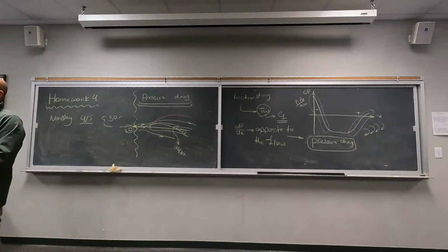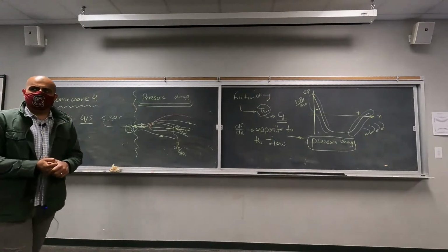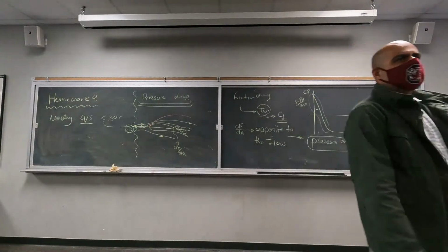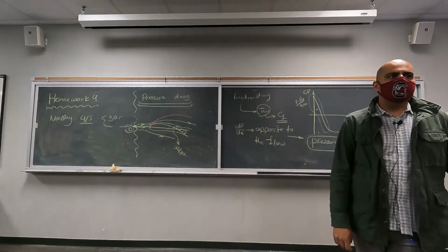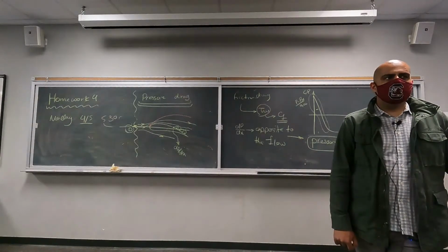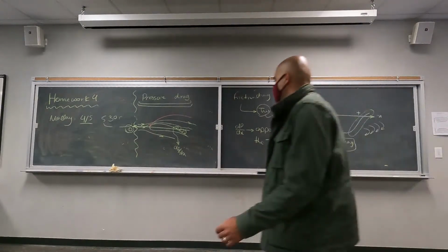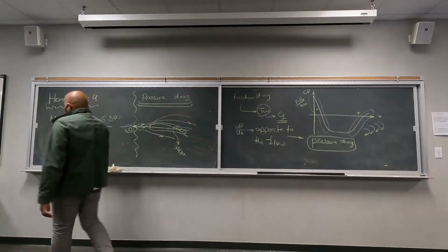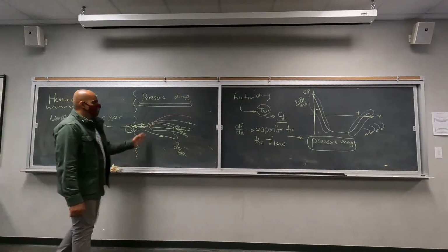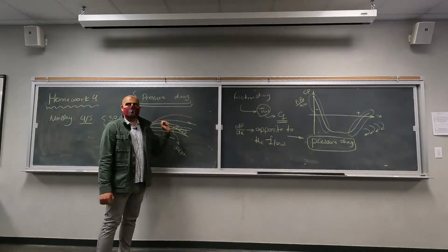Okay, yes. So the drag force is generally in the positive direction if you draw an axis. That's right. But the adverse pressure gradient, you said that it pushes the airfoil forward. So would the net effect somehow reduce? Not the net effect. The total pressure difference between the front and back of the airfoil is going to be different.